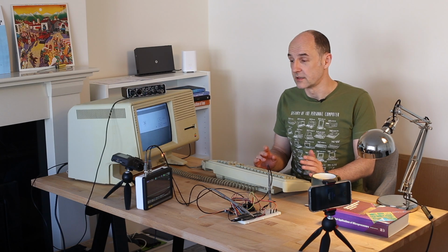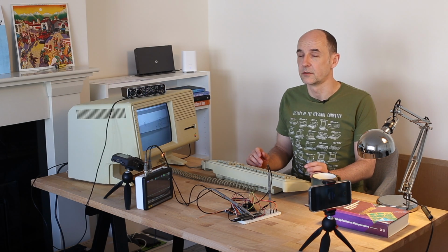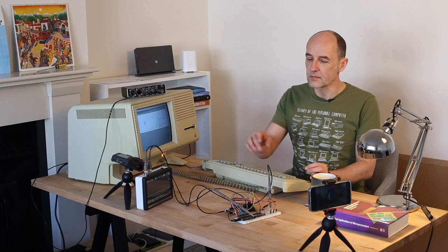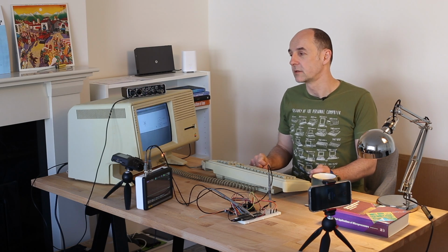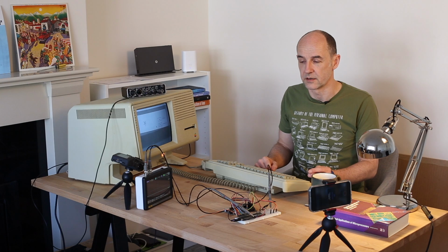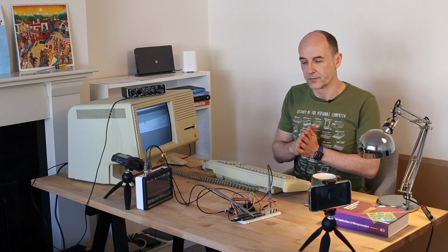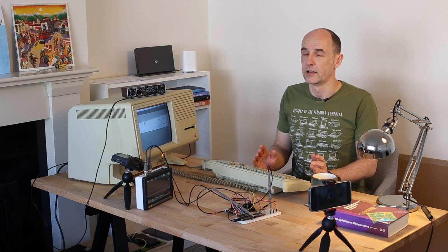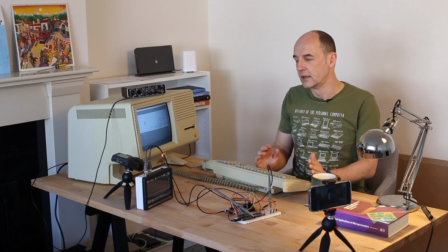And as the last remark, an interesting thing to mention is the fact that Lisa initially was meant to have a slightly different sound subsystem. In pre-production models, the sound generated from within the 6522 was not meant to go straight to the amplifier. Currently in production systems, it goes to a relatively simple amplifier circuit. It not only amplifies the sound, but also divides the frequency by 2. But in the pre-production models, apparently, and it can be read in pre-production documentation, which is available online,